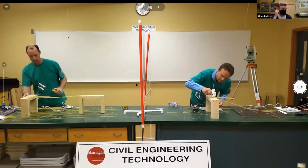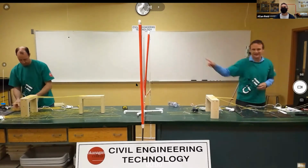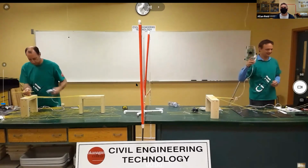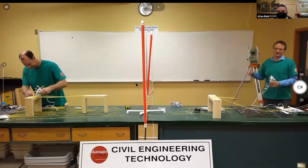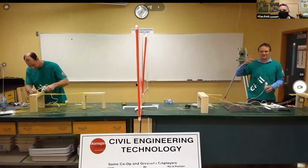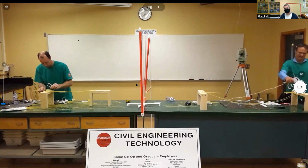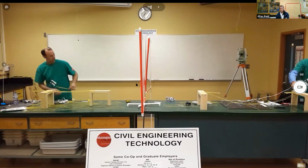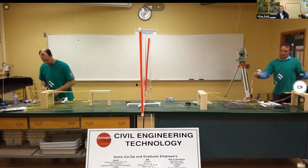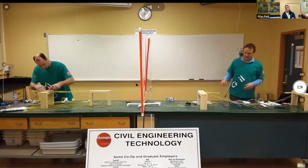So what are your hands-on labs like, Chris, with your surveying equipment? Oh, it's pretty fun. We go out there and we tie into some lock corners next door here. What's a tie-in, Chris? Oh, we shoot them with the total station so we know where they are, and we get the instrument oriented so it knows what way is north and which way it's facing. And then, for example, you tie into a couple of iron pins, and that's what marks all the property boundaries. Right. And then whatever you want to lay out, in this case, we picked up all the back of curbs and catch basins so we could do a drainage plan for the parking lot.